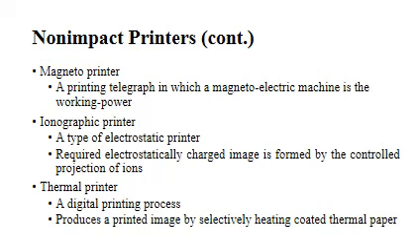The printer sends an electric current to the heating elements of the thermal head which generate heat. The heat activates the thermosensitive coloring layer of the thermosensitive paper which changes the color where heated. Such a printing mechanism is known as thermal system or direct system.